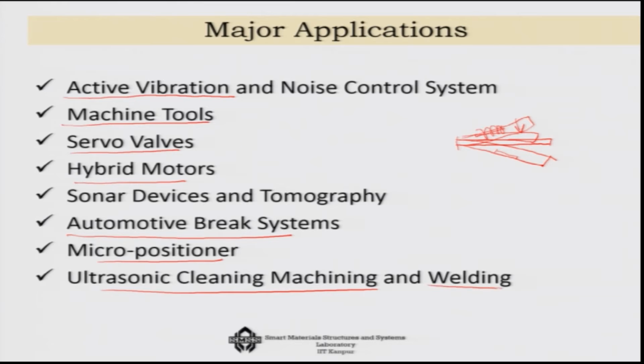You can also use a similar magnetostrictive material for ultrasonic welding. One advantage of this material over piezoelectric material is that piezoelectric material, because it is basically capacitor in nature, may get discharged with respect to time, but magnetostrictive material would not. So, it is actually more rugged.